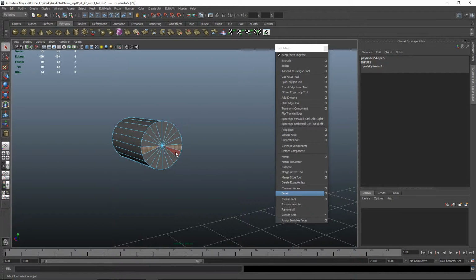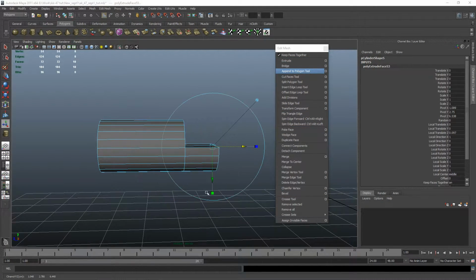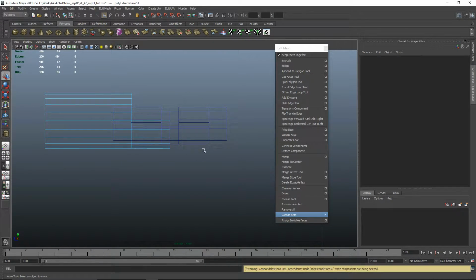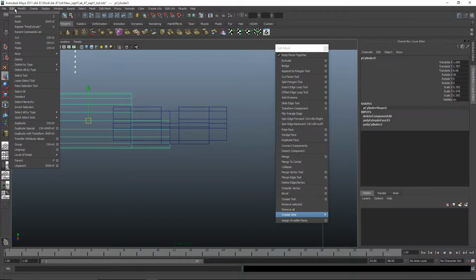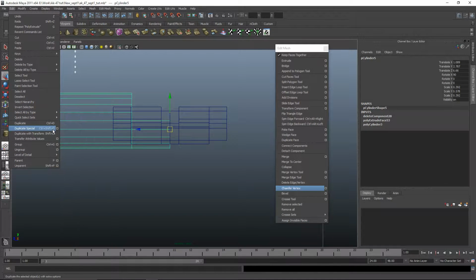And I'm just going to isolate that in a perspective view. And I want to select, hopefully, no, it doesn't want to select by double clicking, okay. Just select one half like so, and extrude to the midpoint like this, delete the faces, insert into the middle, and duplicate special.